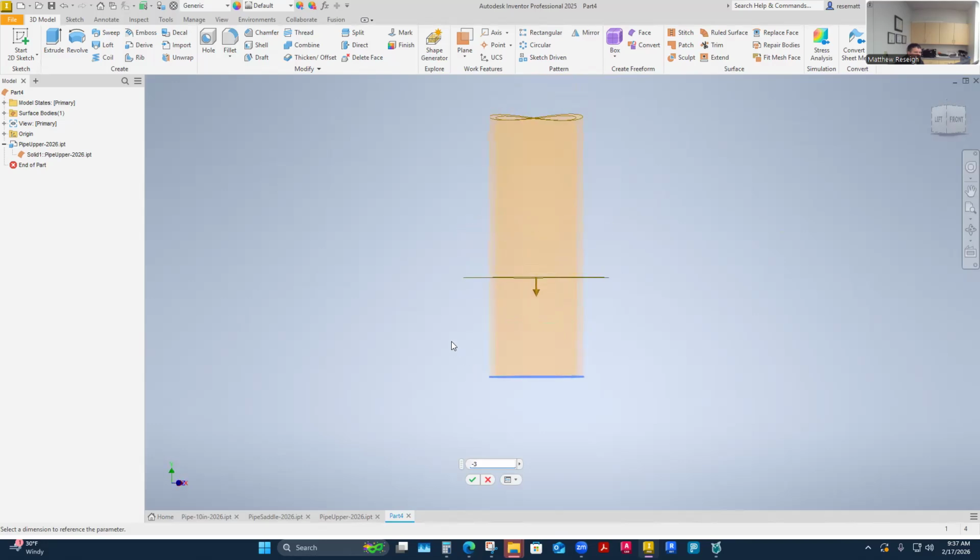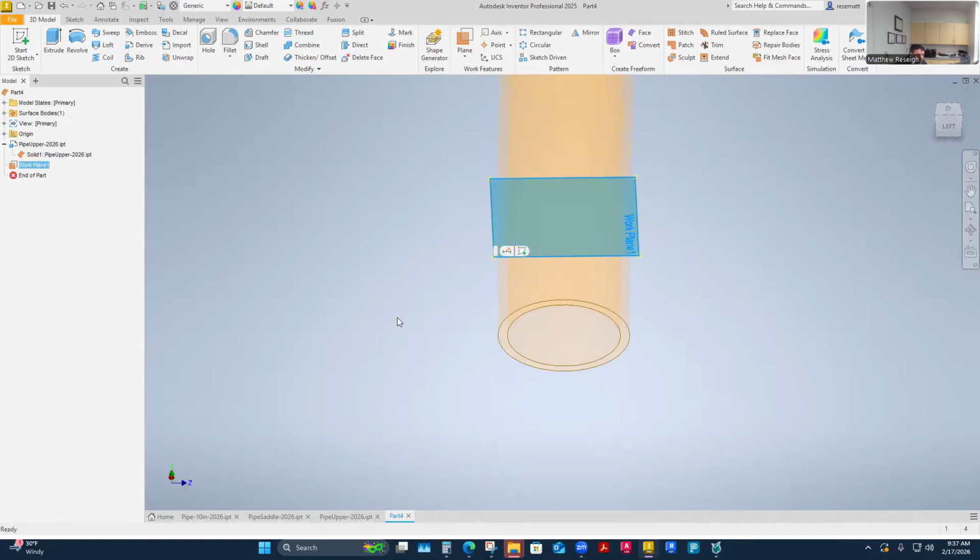That's the wrong way though, isn't it? No, that's correct. That's correct. Essentially, this one's going to be inside the other one, like 3 inches here. And the top, and my part is going to start here, and then I'm just going to extrude it down at the dimensions of a 3 inch pipe. So I'm going to say okay on this. This is just establishing a working plane for where my part lives.